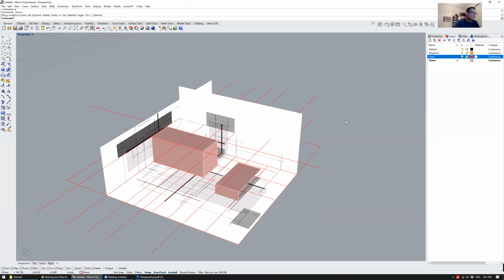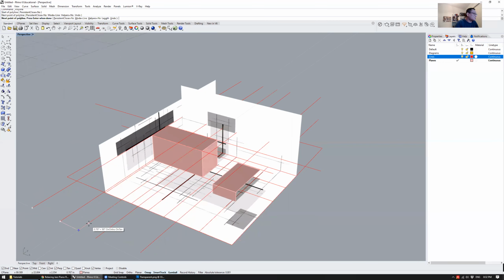Okay, so the last couple of little things I want to show here, besides reinforcing that you should use your object snaps, right? You can turn them on or off. Usually you will have the near snap off unless you're trying to do something on rails like we were trying to do earlier. The snaps are what allow you to more precisely make sure things are actually joining to each other, so you should almost always be drawing with your object snaps on.